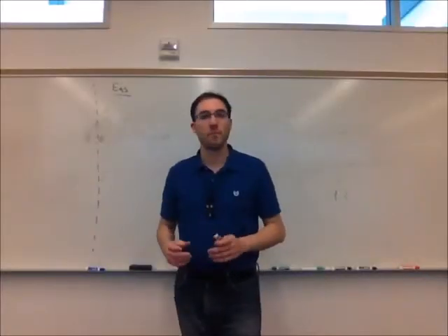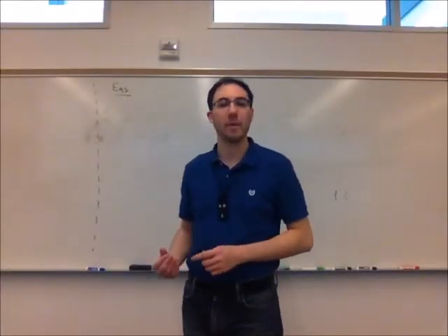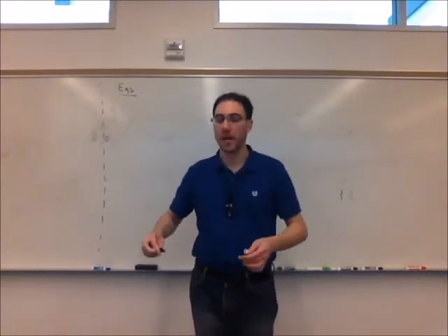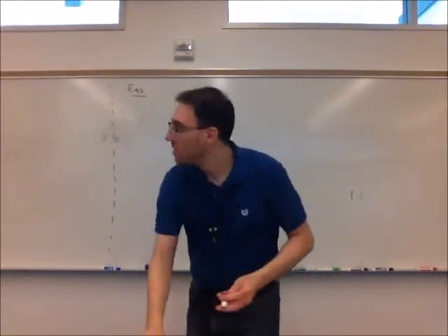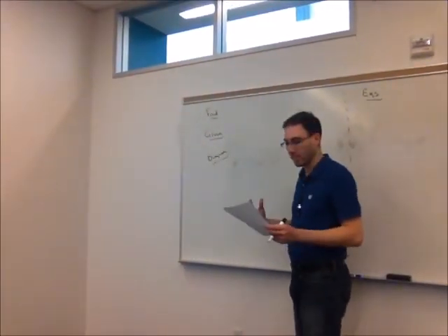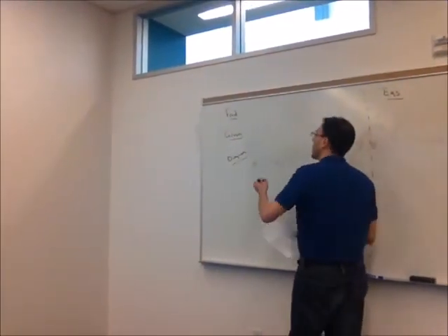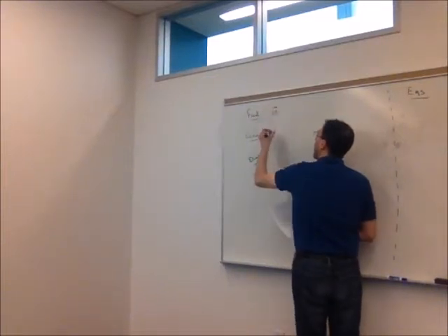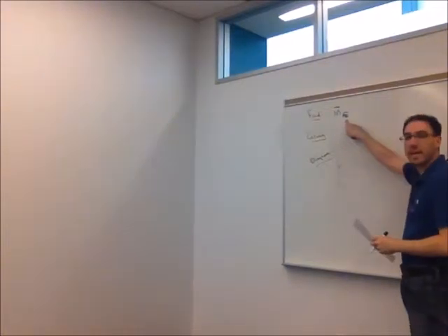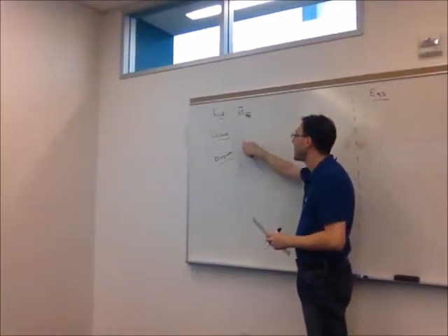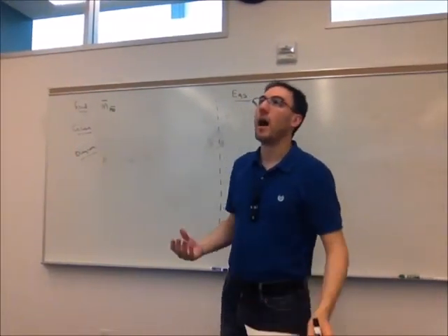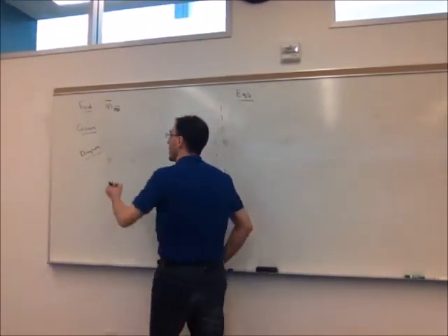In this problem, we're looking for the moment around direction AB, or axis AB, caused by that single force acting on the pipe. So, mathematically, in the find step, we want in Cartesian components what this vector is. We are looking for M_AB, the vector of the moment around axis AB. All that we're given here is the diagram.